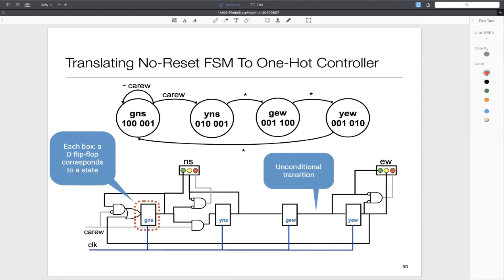So that's manual. The second one is right after power up. Usually there is some special circuitry. When your system starts up, the voltage takes some time to stabilize, and your flip-flops come up in random states, right? Some come up 1, some come up 0, so you don't know where you are. In fact, in our one hot example, it might not even be a valid one hot code. So usually there will be some special circuit which will make sure that the system is in a valid state.